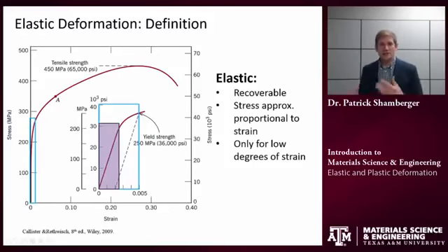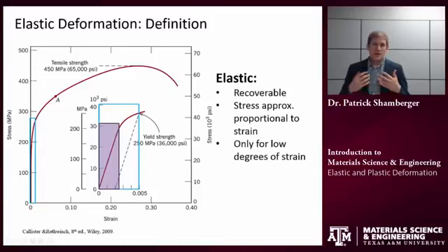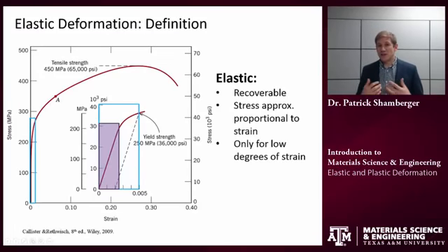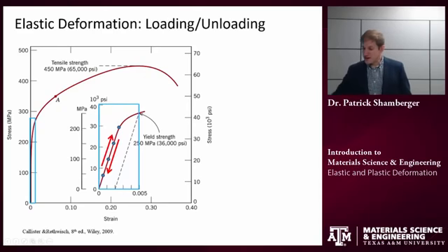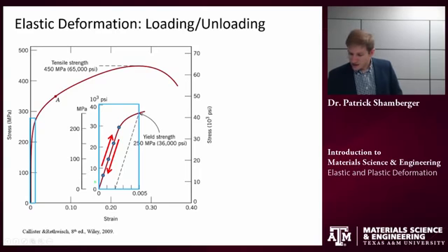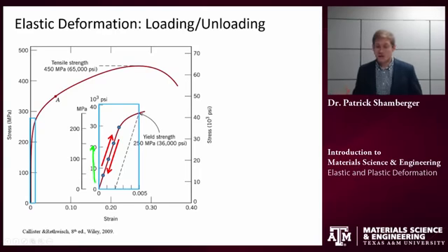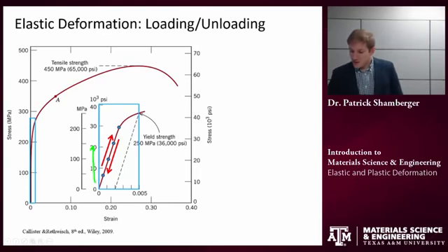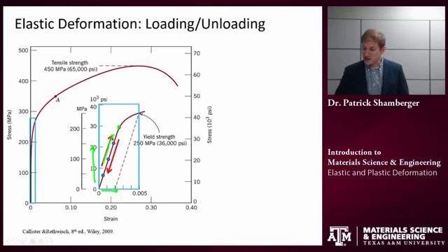Now, you've already seen a stress-strain diagram, so you know that the elastic portion of the curve is typically linear, but more importantly, it's defined by the part with entirely recoverable strain. So that is, if we apply some stress, maybe we're loading the material tensilely, the strain will increase. So I'll follow the stress-strain curve up to some point, say here. If I remove that stress, the strain is going to come back to zero.